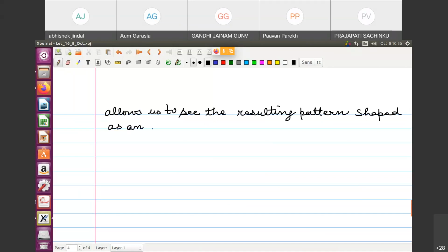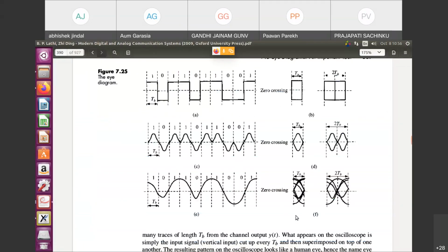Yes, so this is what we wanted. This is the explanation of how the eye got formed, that is, why we see so many lines, and why we also see them below. Because the bit sequence which we are considering would generally be random. It will have some transitions for 1, some transitions for 0, meaning 1 0 1 0.